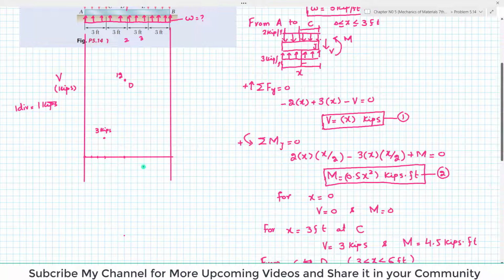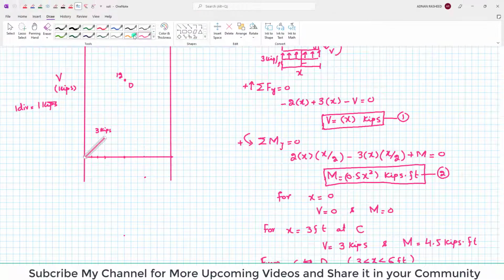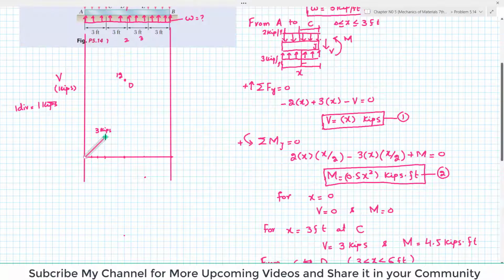And again, at a distance of 9 feet, it will be minus 3, because this is in symmetry, but the sign will change. And at the end, the force will be 0. Now you can join them and you can get the shear force diagram. Join it by using a different line. Here you have to draw it by using a ruler. This will be minus 3, and at the end it will be 0. So this is your shear force diagram. I will mention the values here. The shear force is minus 12, here is 12, here it will be minus 3 kips, and here it will be 0.